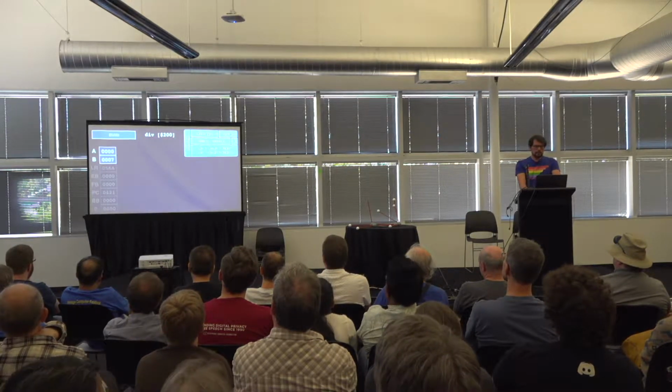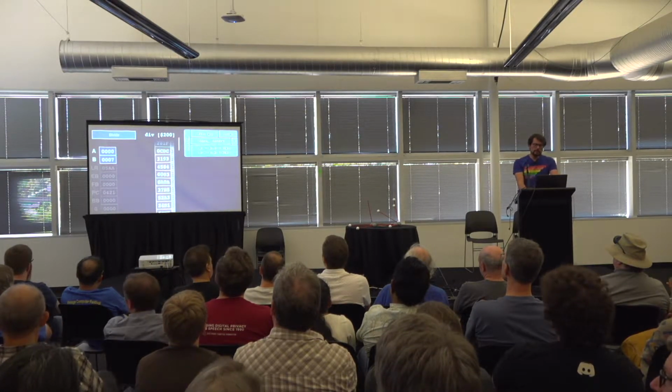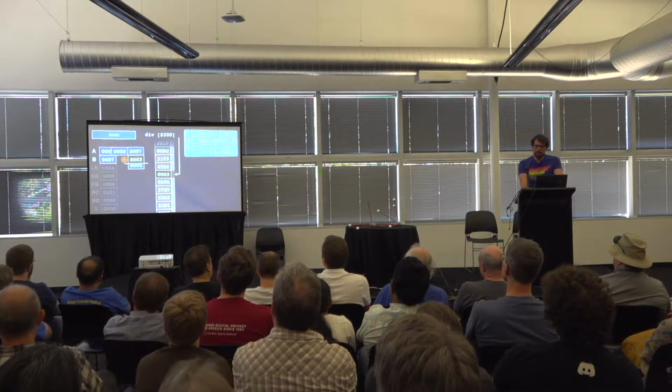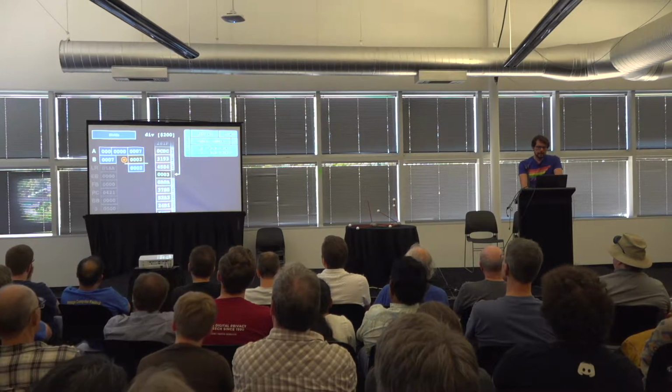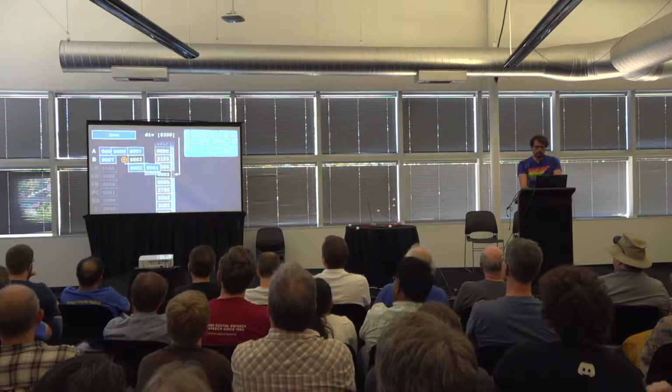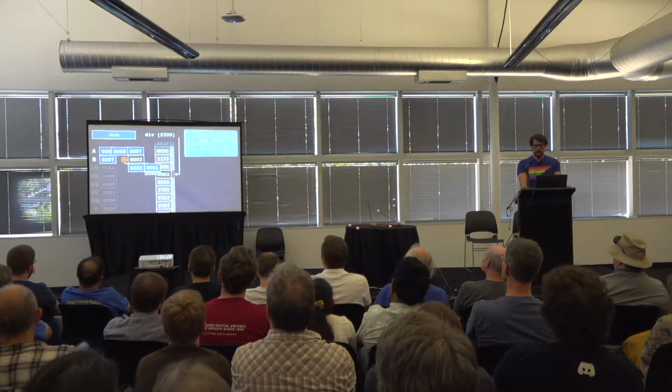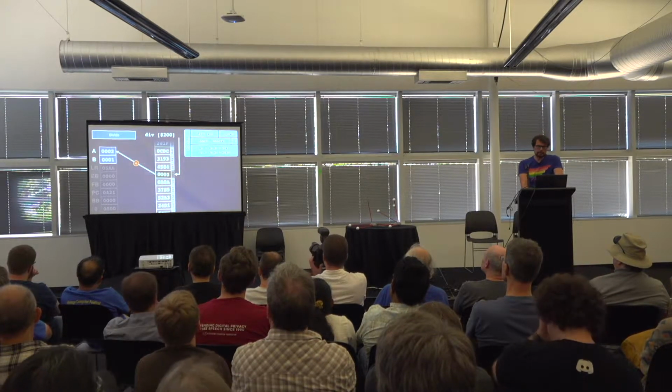Division also works with double words. It takes the combination of the A and B registers as a dividend and a word from memory as the divisor. There are 2 results, the integer result and the remainder. The result is written into A and the remainder into B.